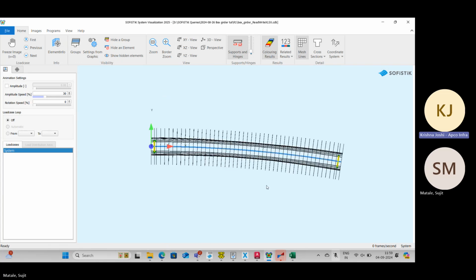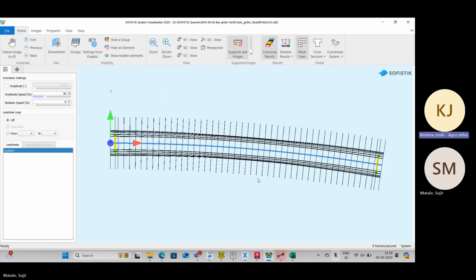For example, suppose you have got a metro rail, we just got like 70 such spans. Then this is the module, 5 meter span length. This is the radius. This is that. Load is this. Give it a run. What it does is finally it generates a report. It does construction stages, updates the loads, does everything, and finally tells you the last page is SLS stress at girder bottom. That is what I'm interested in. And also it tells that in each of the pre-stressing stages, what is the stress at girder top, basically.